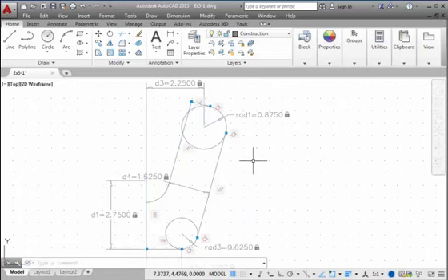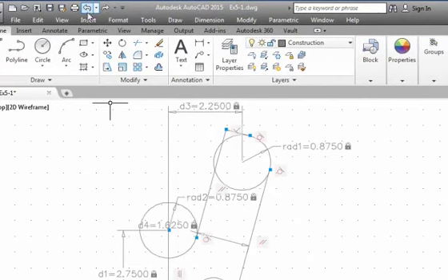With the traditional CAD systems, deleting objects does not change any other entities. In parametric modeling, the parametric constraints cannot exist by themselves. So when we use the trim tool, we are removing geometry, and therefore the associated geometric constraints and dimensional constraints will also be removed. Click Undo to bring everything back. So instead, I'm going to maintain all of the geometric constraints and dimensions. We will create the necessary geometry on top of the parametric sketch.